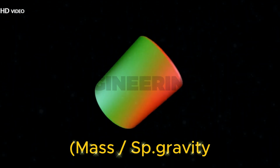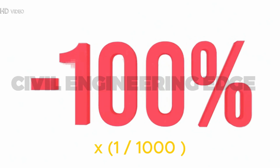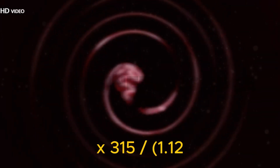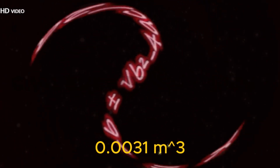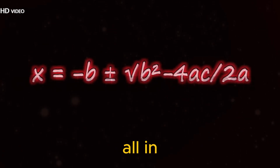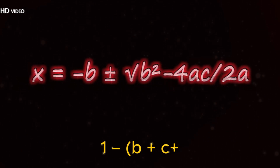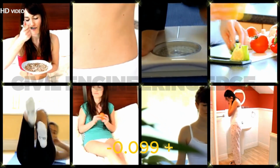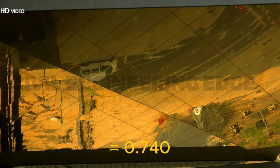D. The volume of admixture equals mass over specific gravity times 1/1000, equals 1.1% of cement, 1.1 percent of 315 over 1.12 times 1000, equals 0.0031 m³. E. Volume of all-in aggregate equals 1 minus B plus C plus D, equals 1 minus 0.099 plus 0.158 plus 0.0031, equals 0.740 m³.